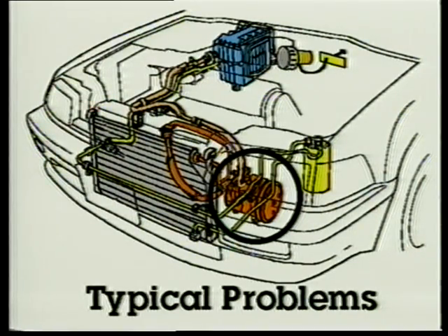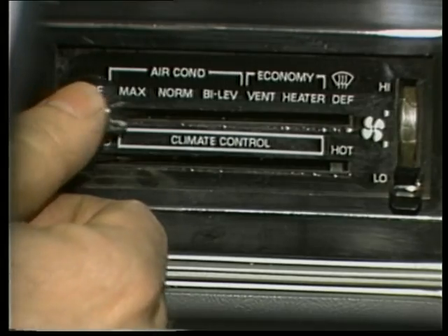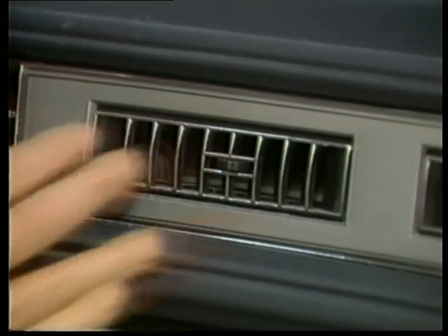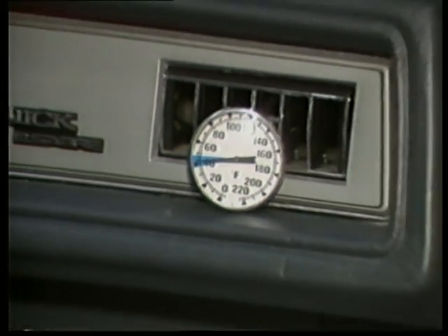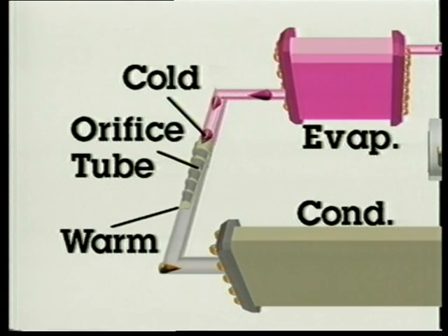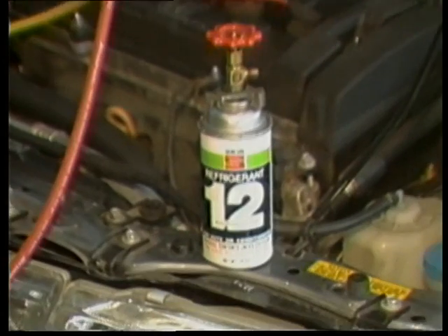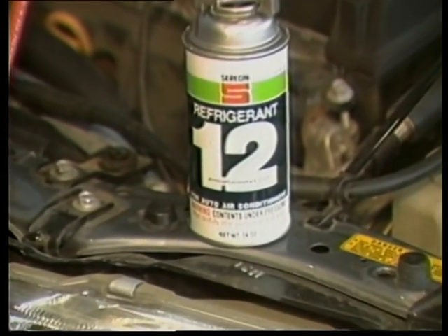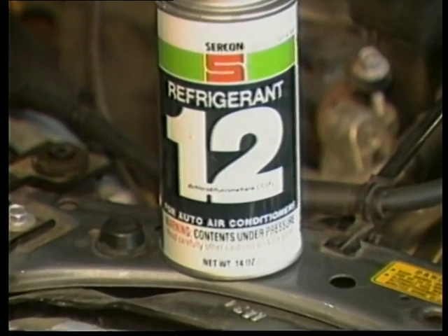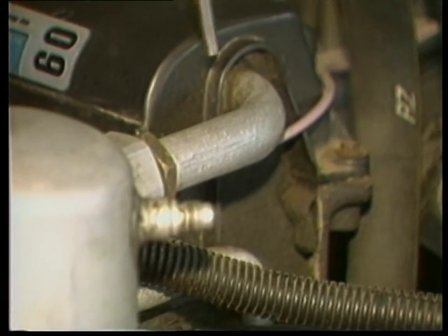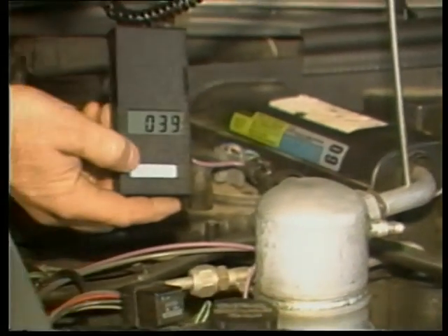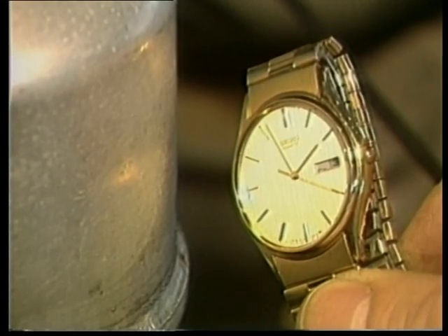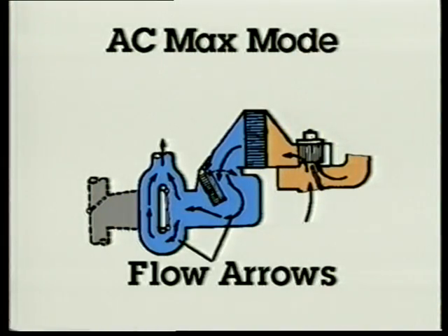This video will use down-to-earth methods to demonstrate how to find the source of problems in today's automotive air conditioning and heating systems. It uses live-action video supported with interesting computer graphics to demonstrate how to inspect, troubleshoot, and analyze symptoms and problems. It covers basic inspection, checking control head and air door action, feeling and measuring line temperatures, listening for abnormal and normal sounds, as well as other techniques for finding troubles.